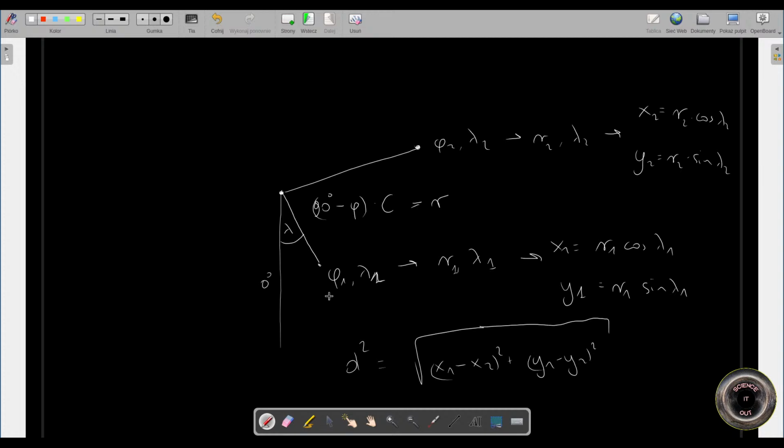So that's how we can calculate the distance. And if we have the reverse problem, so we have some direction which is at azimuth alpha, again we need to calculate the vector that is pointing north, the vector that is pointing east. So vector north in this case will be, so let's say we are at this point x1, y1, so vector north will be simply minus x1 minus y1, and vector pointing east will be this, only rotated 90 degrees to the east.